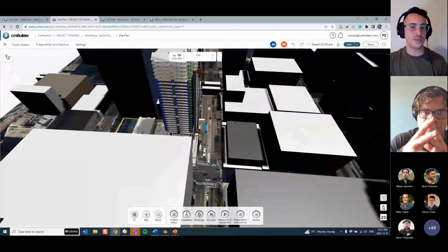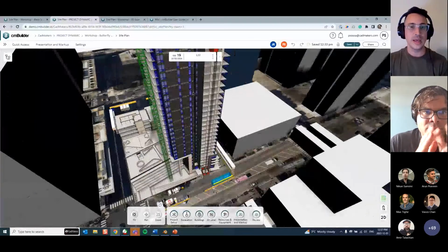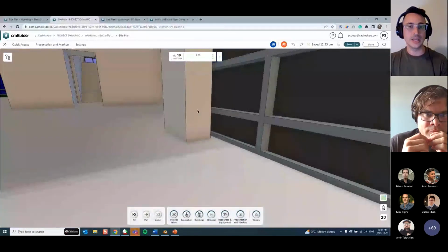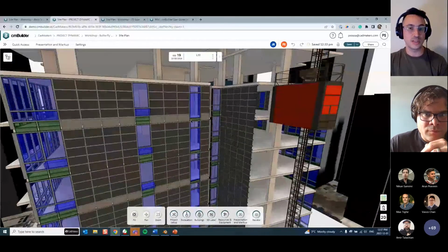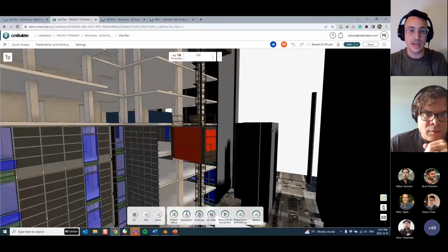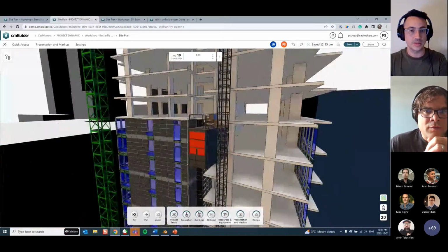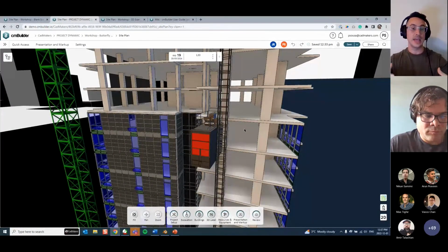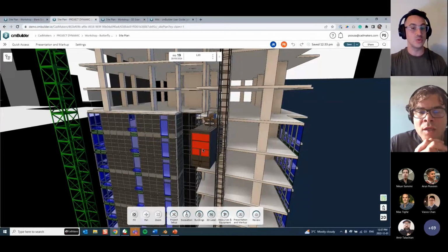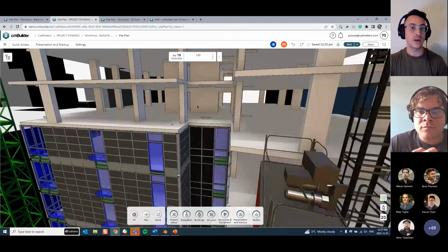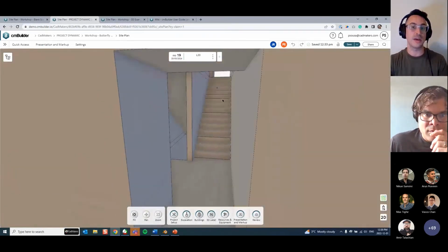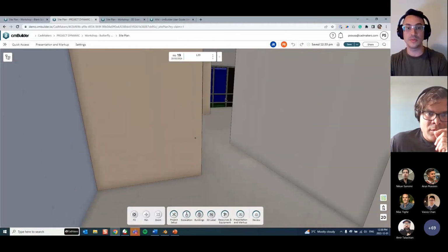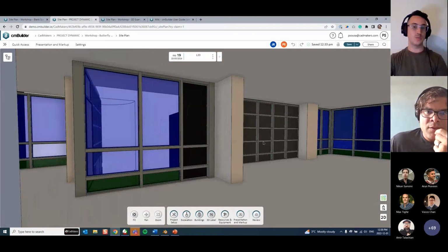So this is a way for you to navigate and move things around faster, but also keep in mind that you can always middle click with your mouse to define the zoom center and rotation. If I middle click on this hoist over here, now my rotation is according to that hoist. This is super helpful, because sometimes you have models that have a lot of stuff inside and you want to go into enclosed spaces. Using the middle click will help you navigate according to specific locations. For example, if I want to navigate according to this stair and go down the stair, I can middle click, zoom in on that location, and then move exactly where I want to move, right?